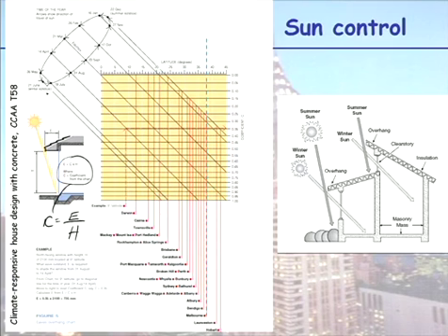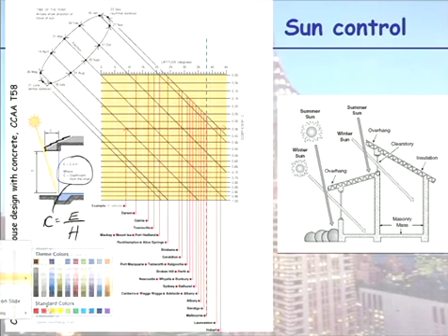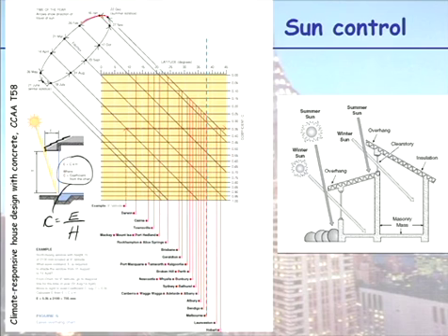This ellipse shape here relates to what amount of sun you want to block out. If I said I want to block out all of this sun from my building, from the 17th of October through to the 24th of February, so through my warm months, I would come down this diagonal line here, and where it intercepts my blue line, that is a value of, I'll just call it 0.5 to make my maths easy. So that's my value of C.